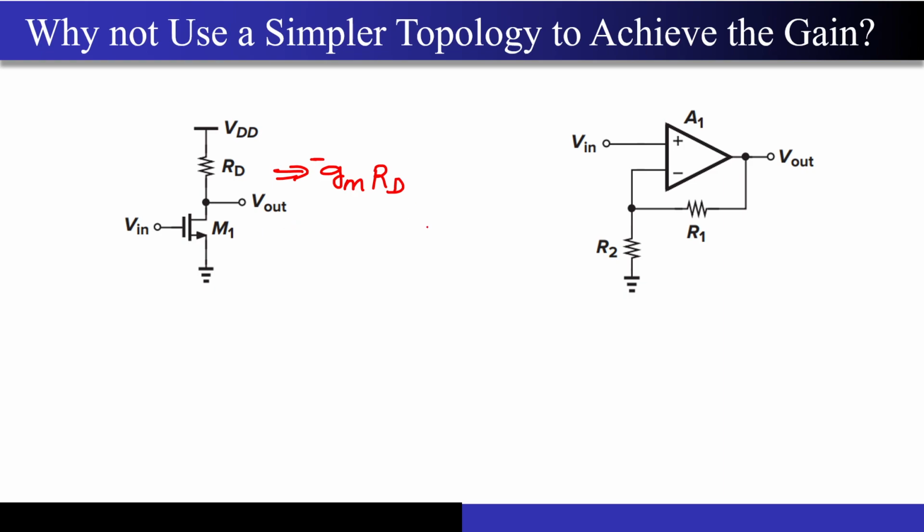Right, now you know that when you try to fabricate a chip, there is something called PVT variations. Now what are those PVT variations? This is basically a manufacturing process, and every manufacturing process has some tolerances inbuilt into it. So you just cannot get the ideal structure that you want to actually fabricate, right? Let's say you wanted a resistor value of maybe 1 kilo, correct? But you will see that after fabricating there is almost a plus minus 20% tolerance in this value.